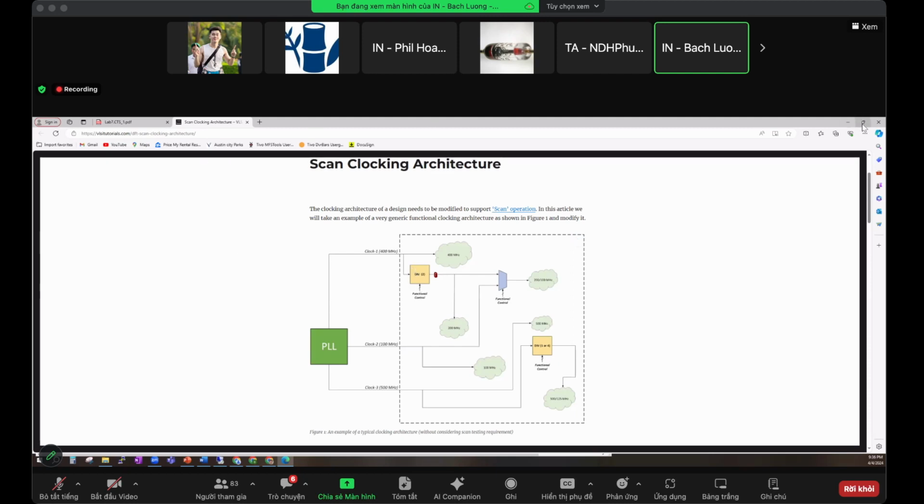Okay. Thank you, Phil. Hopefully after Phil explained, you know what tracing means. Before CTS can balance, it has to trace through different clock groups so that it knows how many sync pins are in each of the groups, so it knows how to balance the different branches across the clock tree.